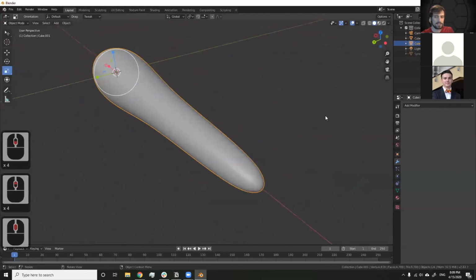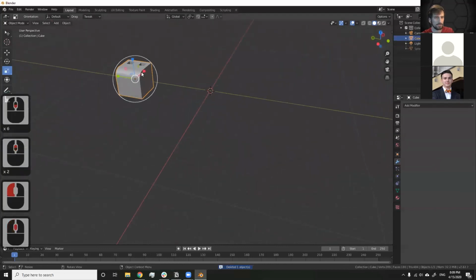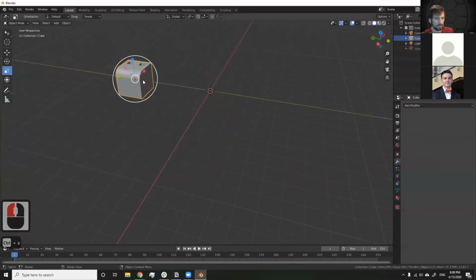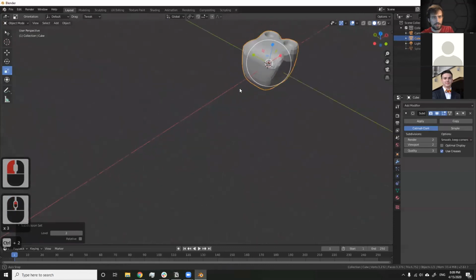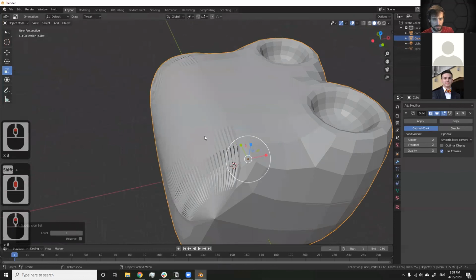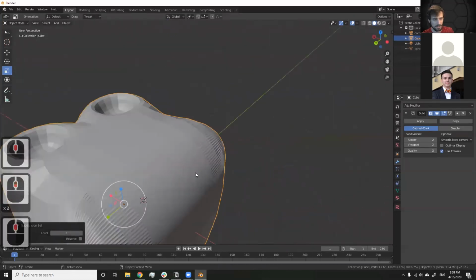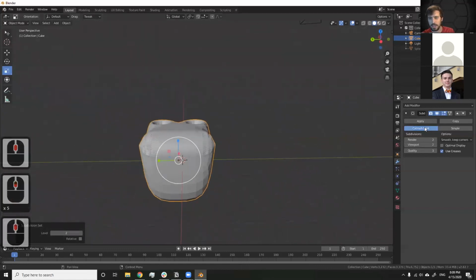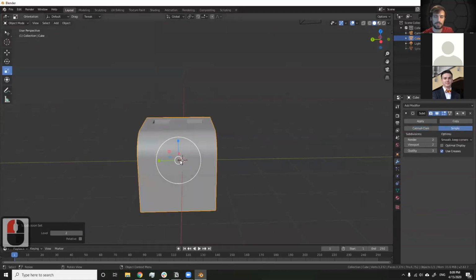And one last thing, if we go back into the subdivision modifier, so if we look at our default cube that we've kind of edited stuff around with on that, remember when we did the subdivision on it, it kind of looks weird. It kind of breaks it a little bit. If we look at the smooth fillet that we added across it, it adds this weird ribbing effect that we don't necessarily want. That's because it's using the Catmull-Clark one where it rounds the edges as it adds them in. If you just do simple, it's not going to look like it changes anything.